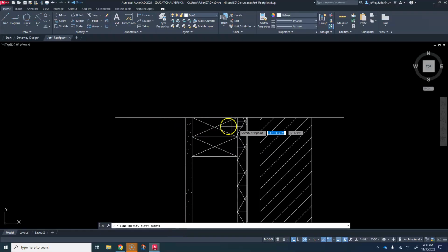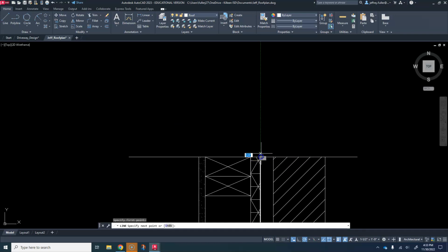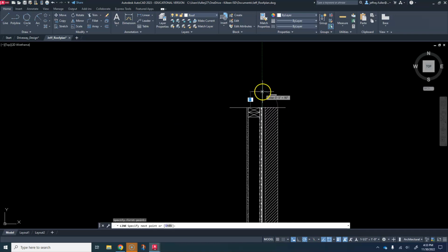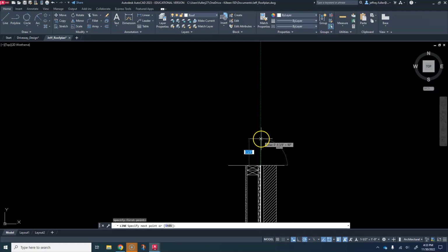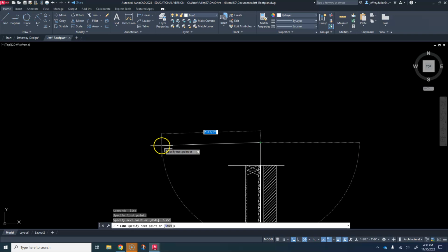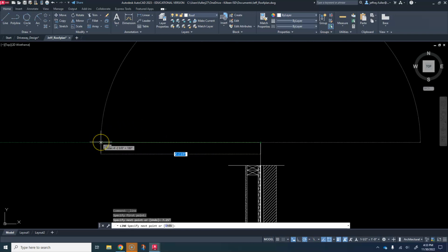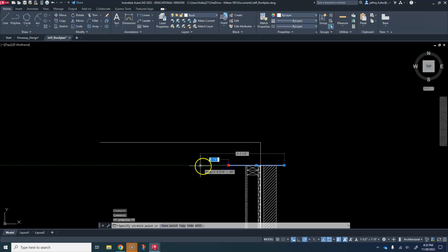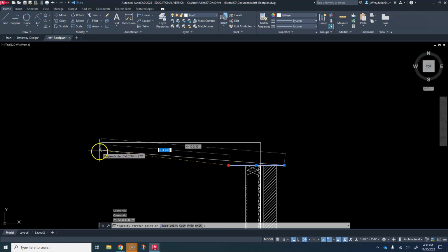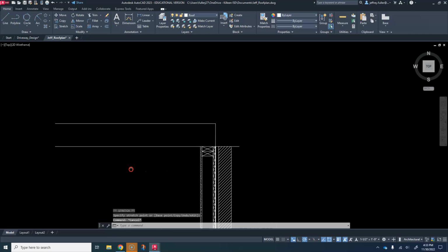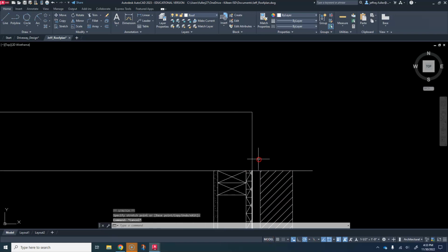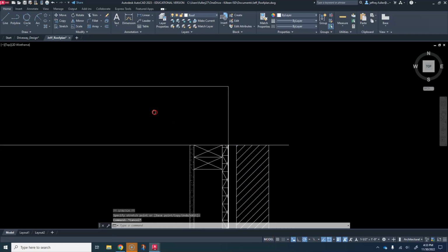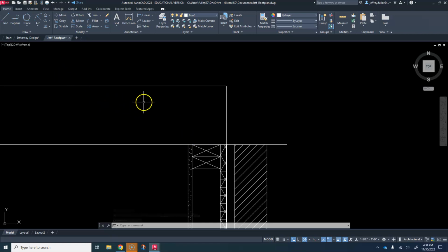So to draw that joist, we're going to go up 7.25 inches and draw across this way. It doesn't matter how far, just draw it. And then we're going to take this line that we made earlier, borrow it, and bring it out to the length of this line. So this is our piece of wood. This is our 2x8. Now the next one is going to be diagonal. It's going to be our rafter.